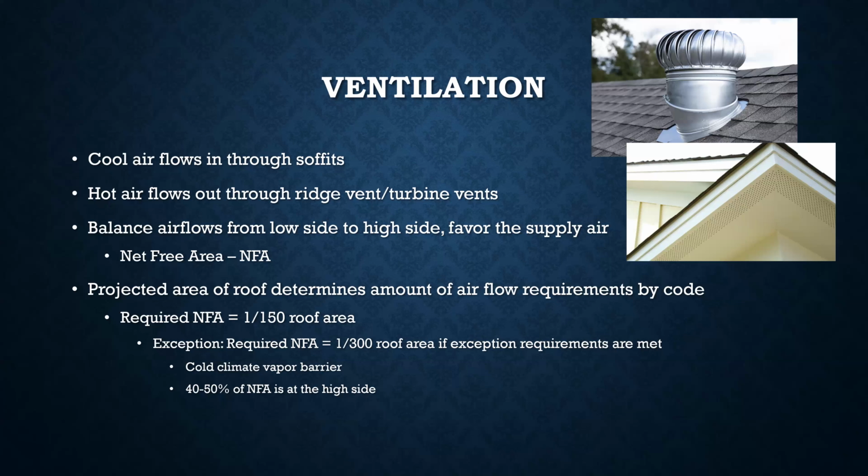The reason is that if you have much more airflow leaving your attic than can get in, it's going to suck the air out of your house instead of drawing it in through the soffits. That's bad, because you're trying to condition or heat the air inside your house. You want to keep the air inside your house, not have it going into your attic. So you want to favor the supply of air so that you don't get suction in your attic pulling air out of your house.